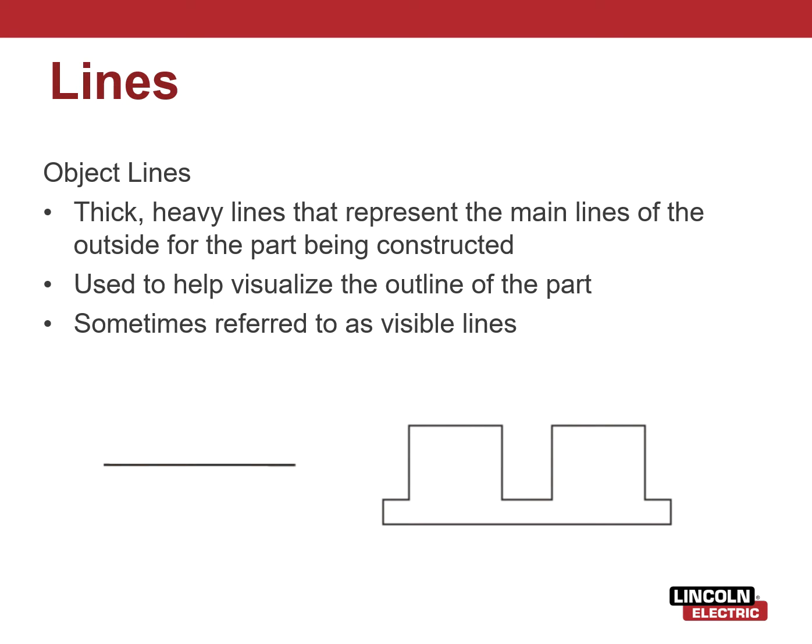Okay, so our first set of line types, right? Different types of lines. It's going to be an object line. This is basically, if you're looking at a drawing, if you've ever messed around with SolidWorks or Onshape or AutoCAD, any of those 2D or 3D design programs, the object line is basically the part. Just think about the part, and you can change the views around, but the outline, what identifies the part, those are called object lines.